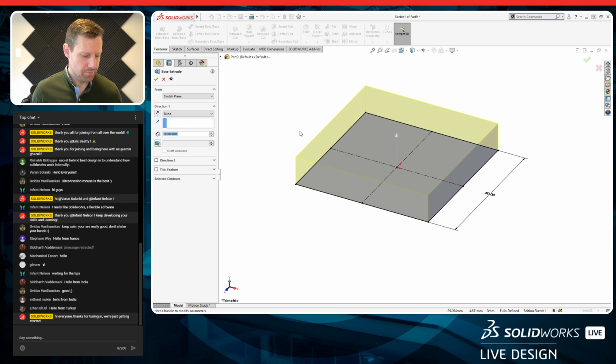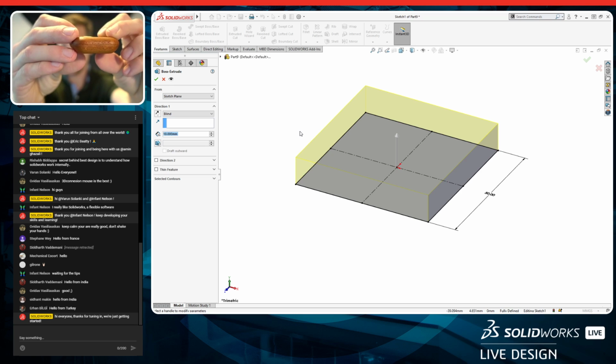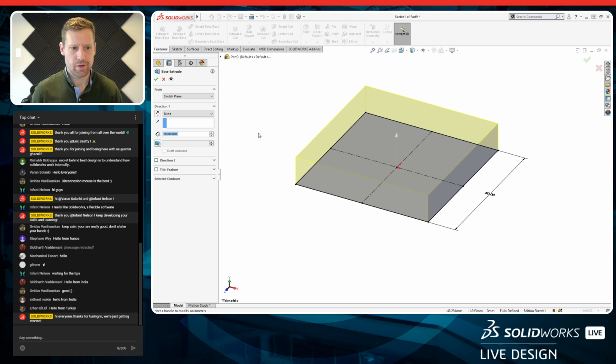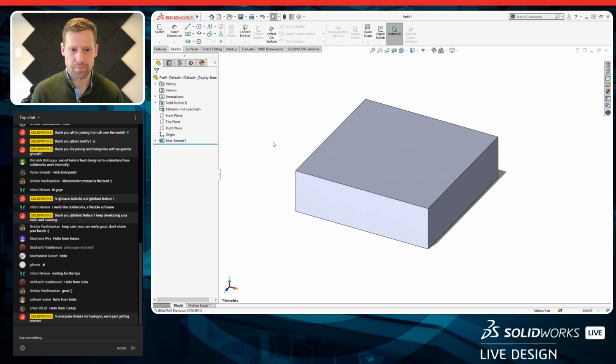So that's really nice. Now I do want to point out with this product that the top is maybe a little bit thinner than the bottom. So let's just say the top's going to be 5 millimeters for now. And we'll extrude in a second direction as well. We'll make that 10 millimeters, and then we'll say check to confirm.